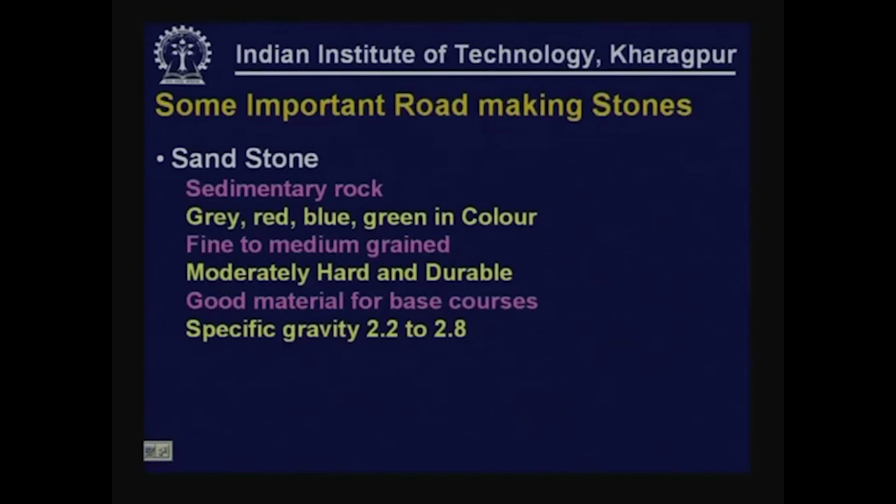Sandstone is another sedimentary rock coming in colors such as gray, red, blue, green. The grains will be of fine to medium size. These are moderately hard and durable, good materials for base course. Specific gravities range from 2.2 to 2.8.